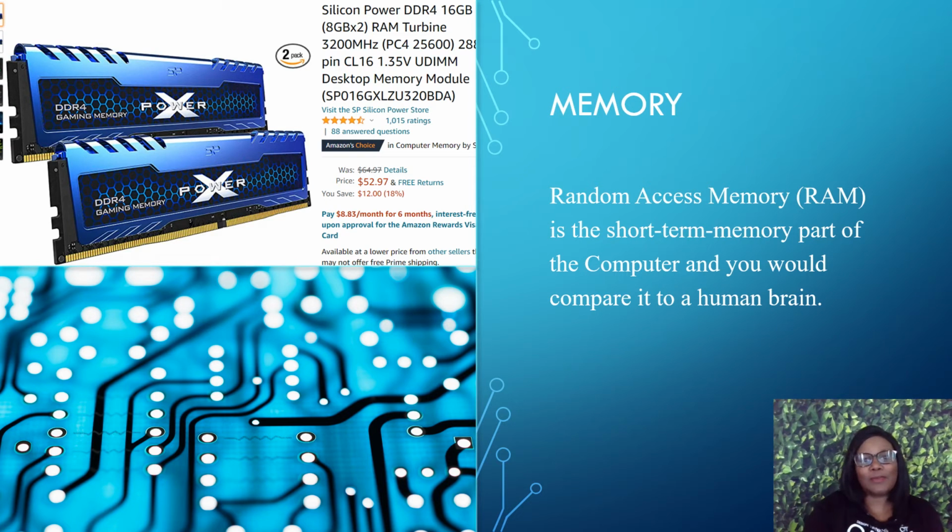Now, according to PCPartPicker.com, the 2x8 gigabyte memory kit that I used for this build is the best price choice within Intel's recommended specifications. The B460 chipset has a maximum RAM speed of 2666 megahertz. Higher speed memory is still compatible, but it will be downclocked to 2666 megahertz.